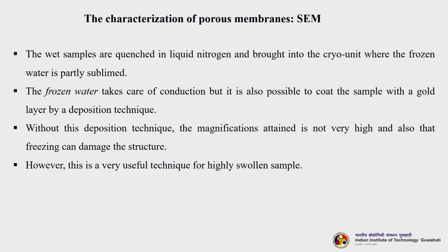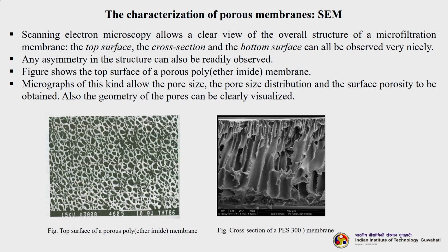Without this deposition technique, the magnification attainment is not very high, and freezing can also damage the structure. However, this is a very useful technique for highly swollen samples. The samples which are highly swollen, highly porous, and contain a liquid inside that gets frozen, are fine in a cryo unit. But for those which are not swollen and not very microporous, it is better to coat with gold. So, this is the scanning electron microscope of a particular membrane.